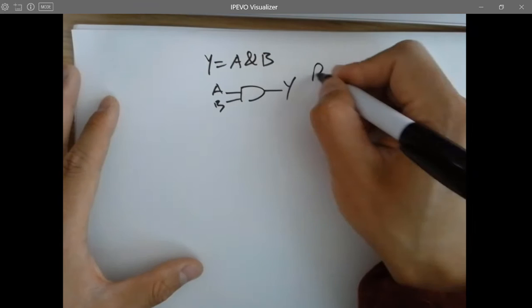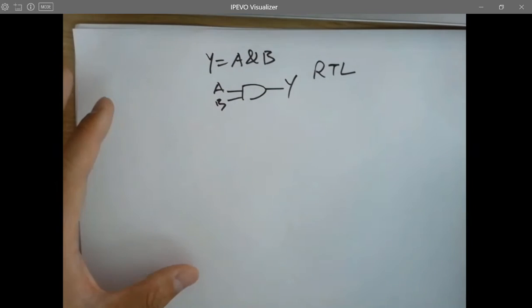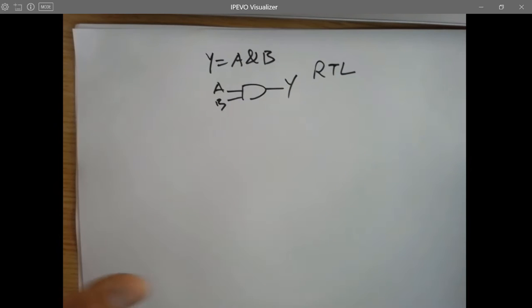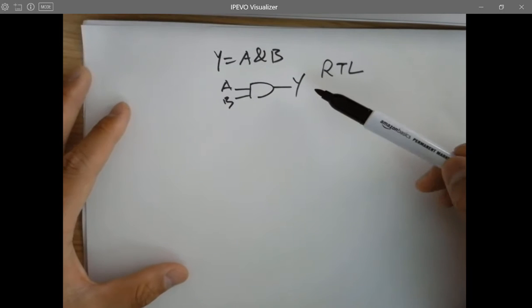So that's RTL. However, if it's behavioral, then sometimes it's probably not implementable. You just couldn't synthesize it into hardware, cannot implement it in the hardware, since you can describe the behavior however you want. It's just totally from your brain, your mind. But not necessarily is it going to be synthesizable, right?